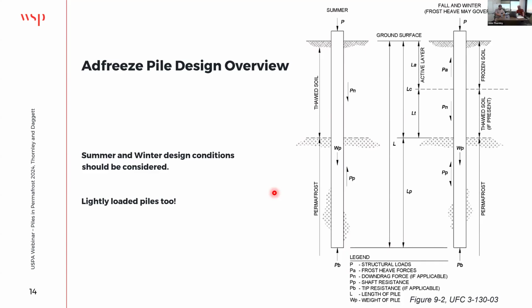So accounting for that in your design is important. With a traditional, assumed frost force of 40 psi, which is commonly used for a lot of designs across the active layer, you could see that is, in most cases, going to control your design, unless we're talking about heavy buildings. So it's very important to consider the frost jacking force on this pile.